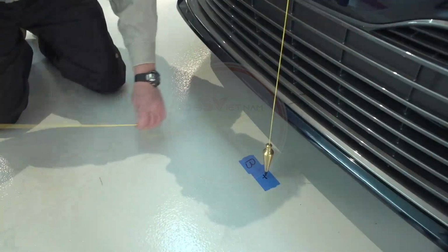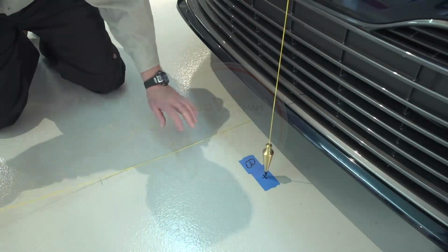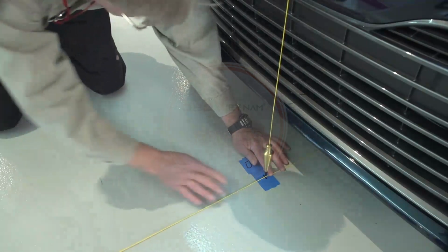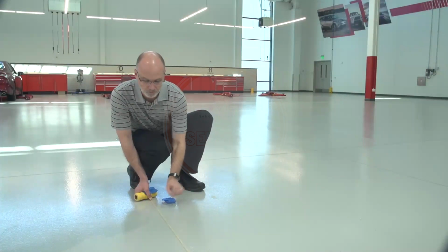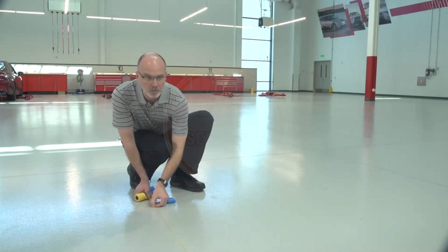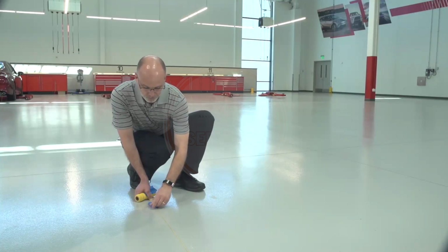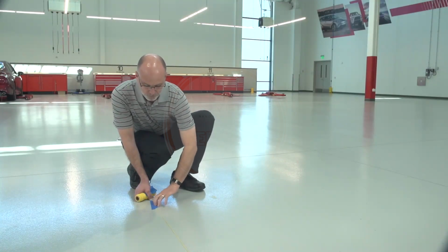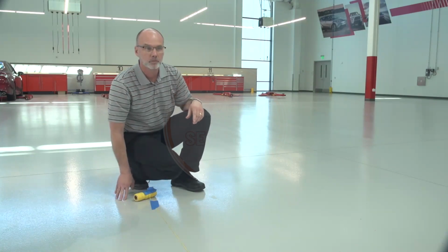Stretch the string you tossed earlier to about 3,000 millimeters out in front of the car, making sure that the string crosses the front center line mark, point B, and tape the string down. Double check to make sure that the string is directly over both point A and point B marks. An assistant helps make establishing the center line easier and more accurate.